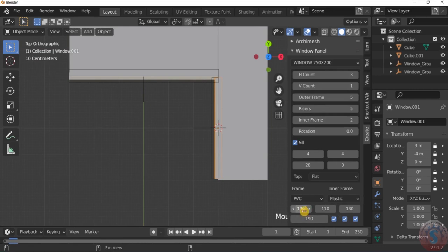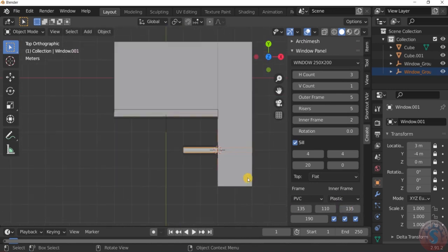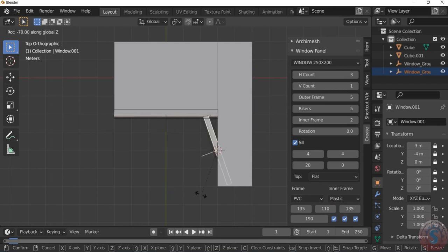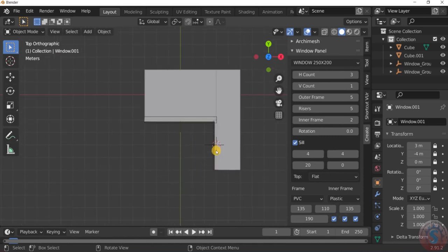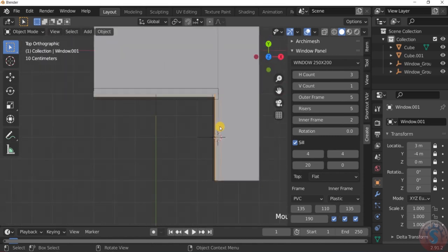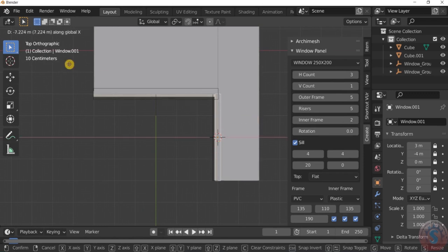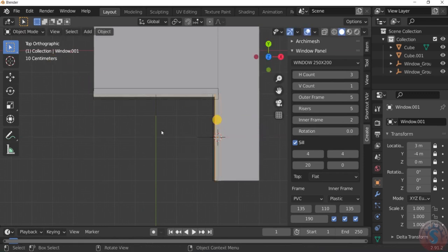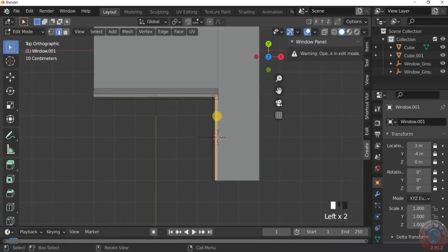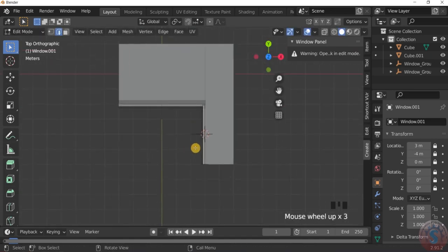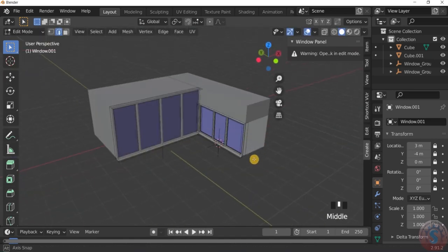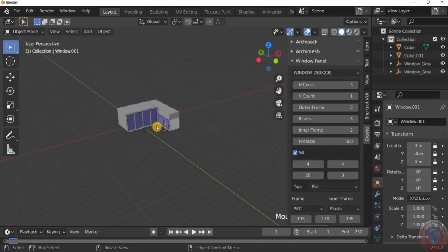This also needs somewhat of an increase to 135, and again to 135, and then R, Z, Control key. It is on the Z position. If you want to move this window here only, you can adjust by using G and X. You can observe I am in edit mode, for example G, Z. Like this you can adjust it here and there, and go into object mode again.